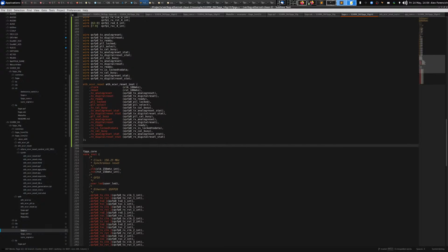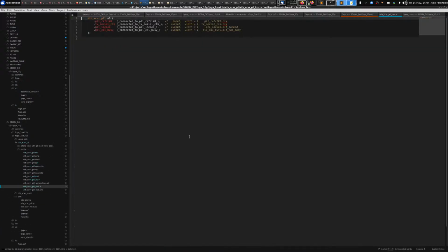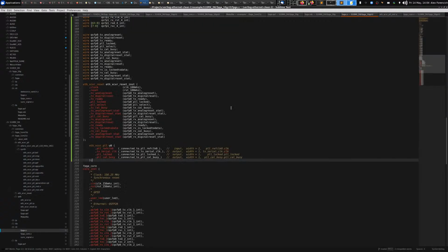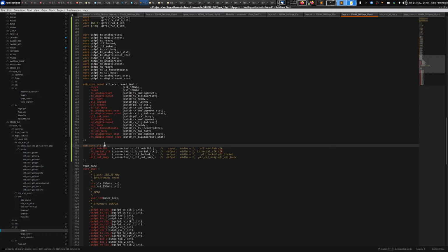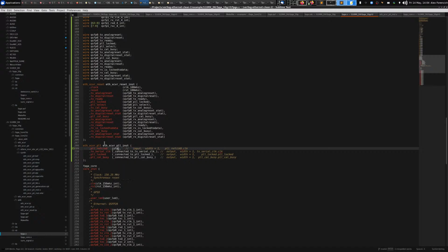Oh, I also need the PLL, right? I need the PLL and I need the PHY. Okay, so PLL, I'll go ahead and do that next. There's a reset controller. Here's the PLL. PLL instantiation. Oh, this is much simpler, right? So go ahead and put that in. The PLL inst. Okay, so ref clock. This is going to be QSFP.